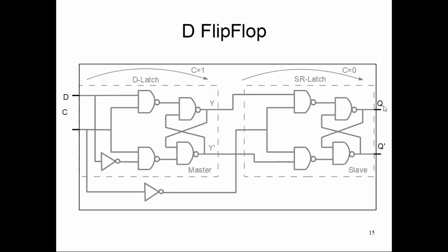And that means we are actually walking towards declaring C as a clock instead of a control. We just introduced a cycle, right? Half a cycle actually makes sure D is not reflected on the Q immediately. It stops it for at least half a cycle, when your C transitions from 1 to 0.